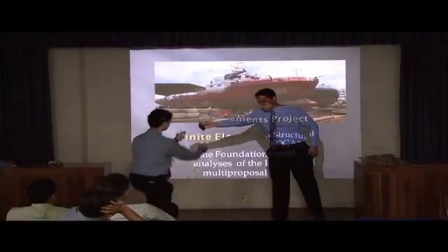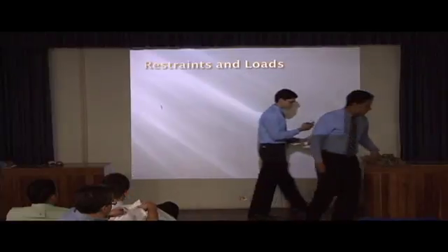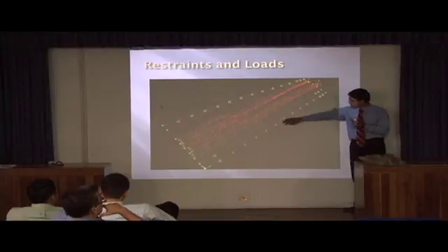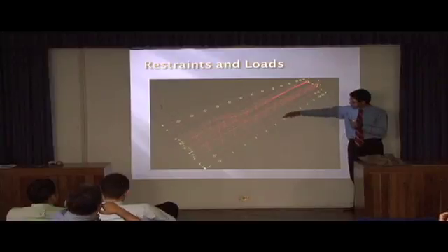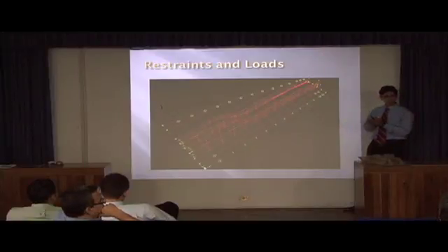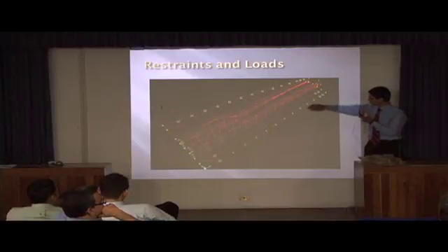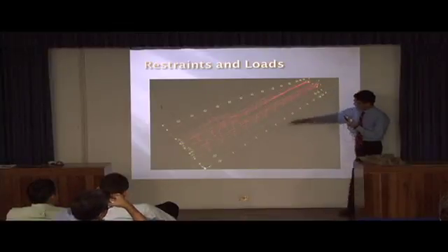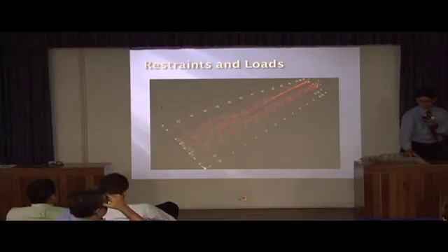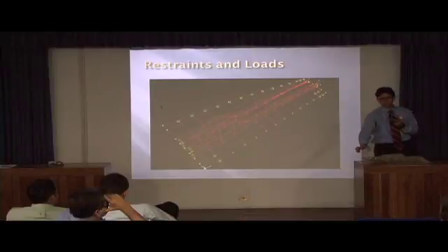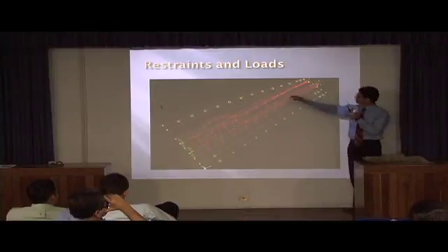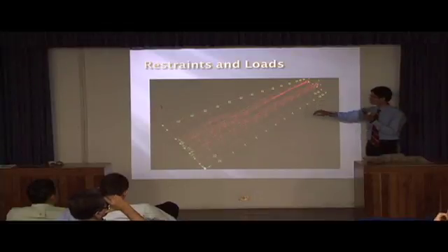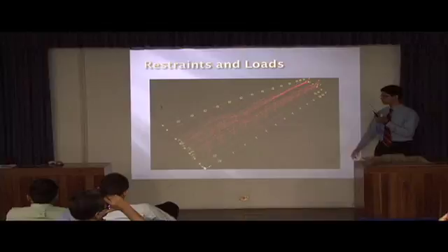According to the finite elements method, we have to apply some restraints to our structure. So we made it in the following way. This could be the center line of the ship. So in this longitudinal direction, we don't have any rotation. In this part of the structure, these nodes and the other nodes, we consider with the bulkhead number 3 and 4. They don't have any rotation in this direction. And the part of the chine that joins with the other part of the hull doesn't have any y-axis displacement or vertical displacement.